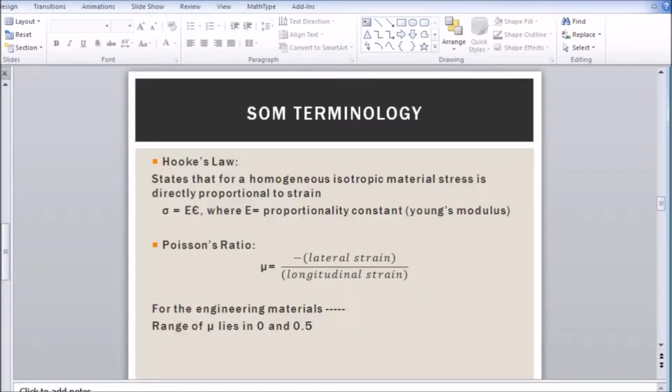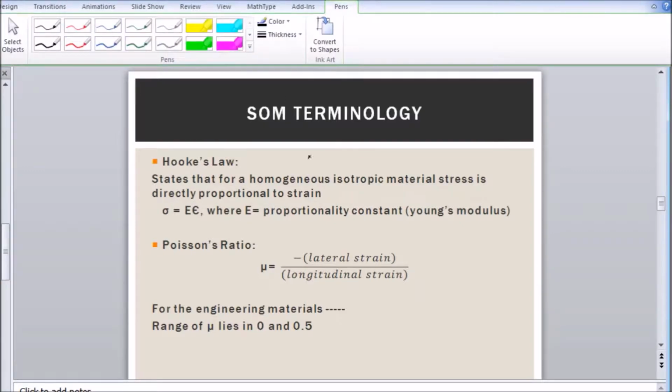Initially, in the stress strain diagram in the earlier classes, we discussed that for any stress strain diagram, for any material, to whatever extent possible depending on the material property, there will be a certain linear region within the elastic region. Up to here, for example, it is the elastic region. Up to this point it will be the proportionality limit, where sigma and epsilon are directly proportional.